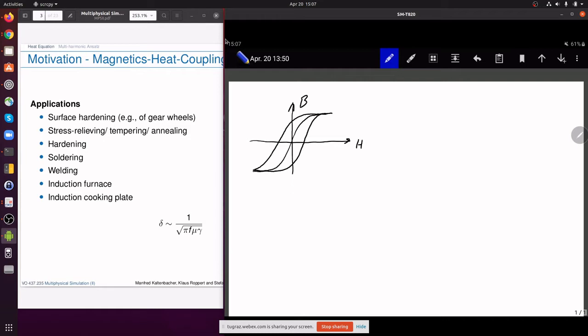So the area in this surface under the BH loop, given by, let's call it, the loop integral of H dB, if we consider it as a scalar problem, is the dissipative loss if we scale it by the frequency, meaning that's the work per one cycle of this hysteresis curve, or the loss per cycle.